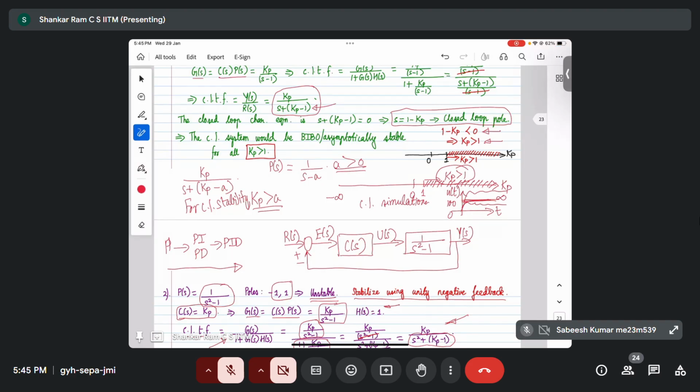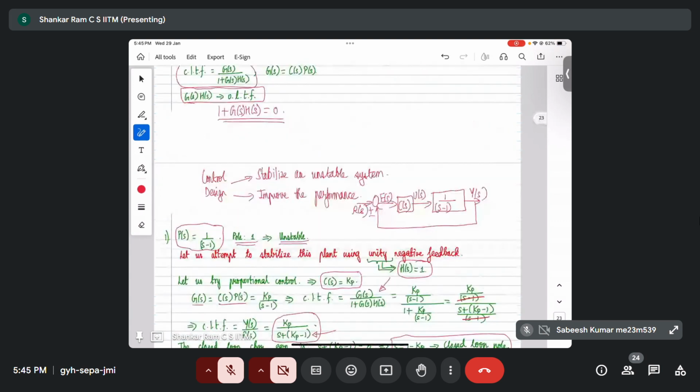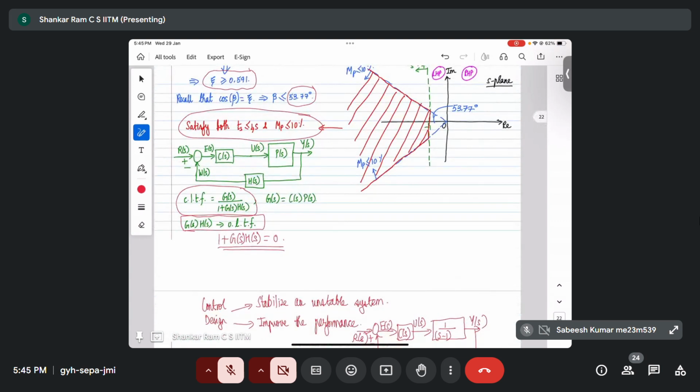So my only question was this Ti and Td, those are the time intervals for which you're going to integrate and the time intervals for which you're going to use for the differentiation as well. Okay, I'll let you complete the question, then I'll give the answer. So my question was this K divided by Ti is what is coming as Ki, or how we are defining the proportional constant, derivative constant, and integral constant.